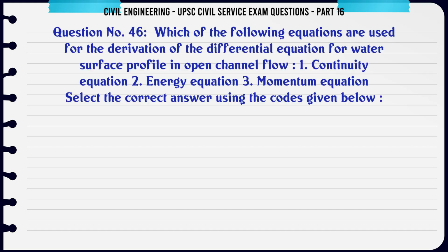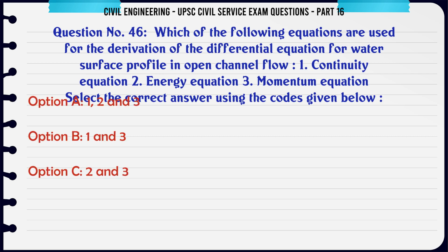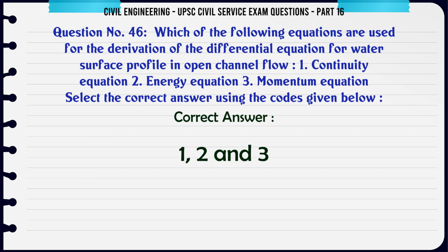Which of the following equations are used for the derivation of the differential equation for water surface profile in open channel flow? 1. Continuity equation. 2. Energy equation. 3. Momentum equation. Select the correct answer using the codes given below. A. 1, 2 and 3. B. 1 and 3. C. 2 and 3. D. 1 and 2. The correct answer is 1, 2 and 3.